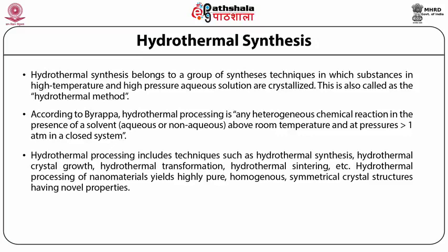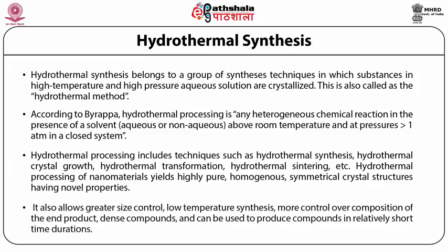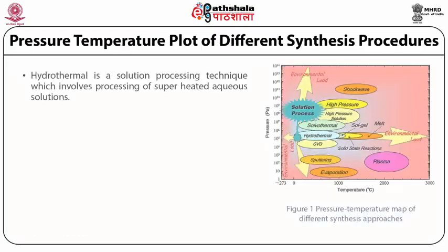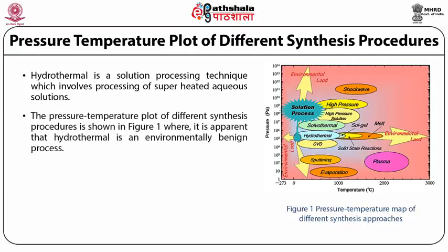Hydrothermal processing of nanomaterials yields highly pure, homogeneous, symmetrical crystal structures having novel properties. It also allows greater size control, low temperature synthesis, more control over composition of the end product, dense compounds, and can be used to produce compounds in relatively short time durations. Hydrothermal is a solution processing technique which involves processing of superheated aqueous solutions. The pressure temperature plot of different synthesis procedures is shown in figure 1, where it is apparent that hydrothermal is